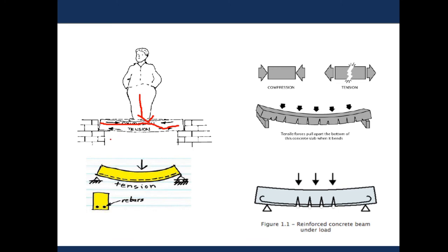Okay, so when it is bending in this shape, it means the bottom fiber will get stretched or tensed or expanded, and the top fiber will get squeezed or compressed.